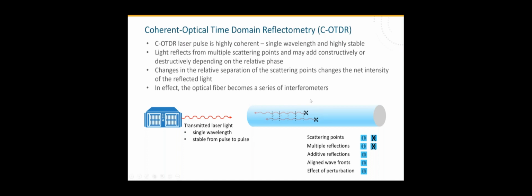And it essentially explains that no matter what the source of the vibration is, it translates into the elongation or contraction of the fiber, and that is what's monitored by the system. One thing that comes out of that explanation is that no signal is required from the end of the optical fiber. So this system always works up to the point of a cut, and that's very helpful in practical real-world scenarios to provide high availability and integrity of a deployed system, as we'll talk about.